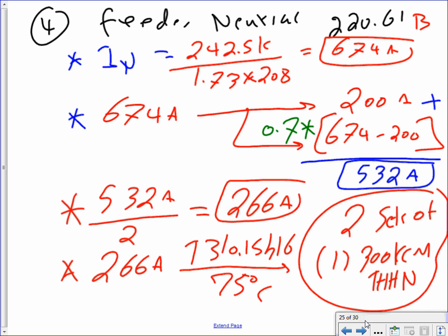That's why we see a panel here. They put a panel here, load everything here, put it on this panel. Done. Another for colleges, every room almost has its own panel, instead of grabbing all these loads, putting them in one panel, and shooting them all the way down to the basement, for voltage drop issues. So, reminder, 225 amp panels, your max up to 300, okay, don't go higher than that. If you need, cut and do multiple panels.